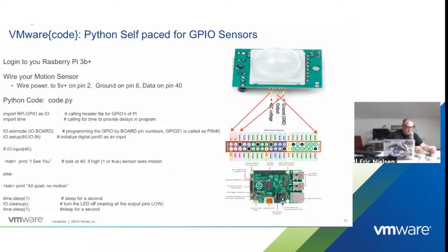And I like to just go grab a GPIO pin down at the end here. So I have it on pin 39. I'll just put mine there on pin 39. And that's it. I've wired up a sensor. Now, you can wire your sensors however you want. They make little bus connectors. You can get bus connectors, ribbon cables, or you can just use these little ones for messing around.